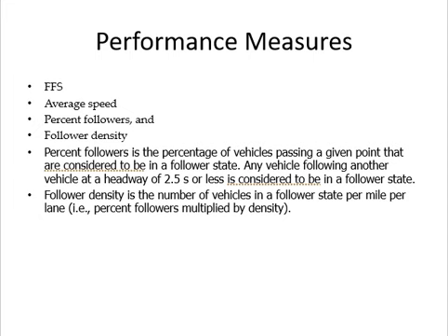If you are taking the average when the traffic is low, then that will become the free flow speed. This is what you are doing in the term projects, right? I asked you to collect speed data and take the average. That is average speed, but if that average is taken in low volume conditions, that becomes free flow speed. So these two we know.